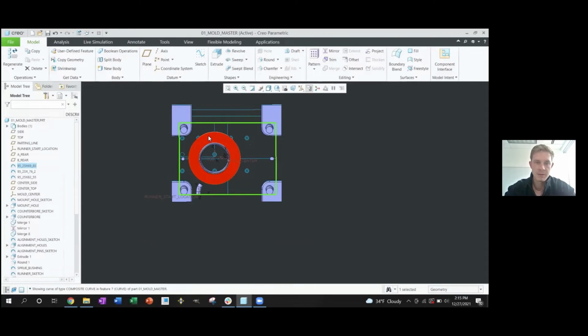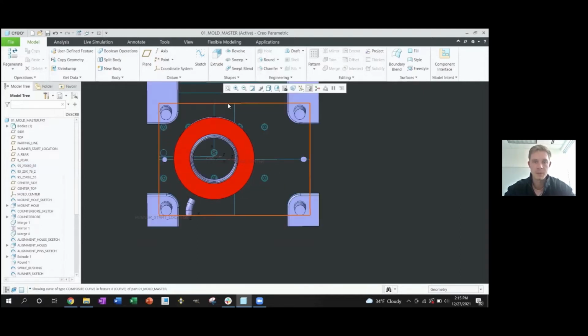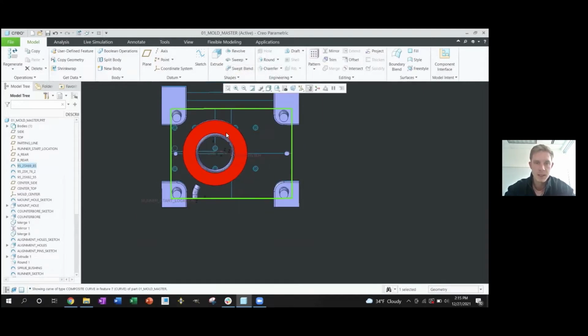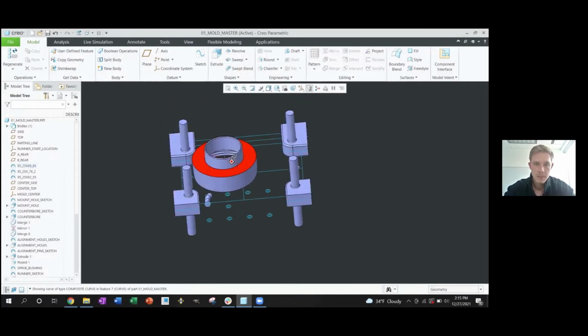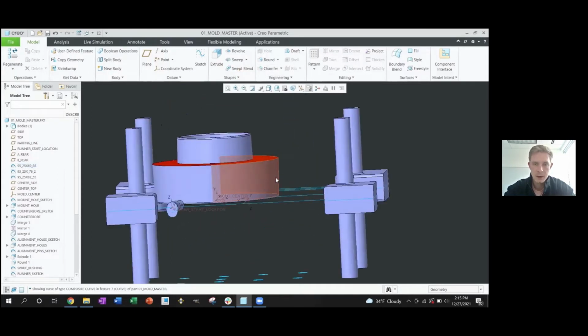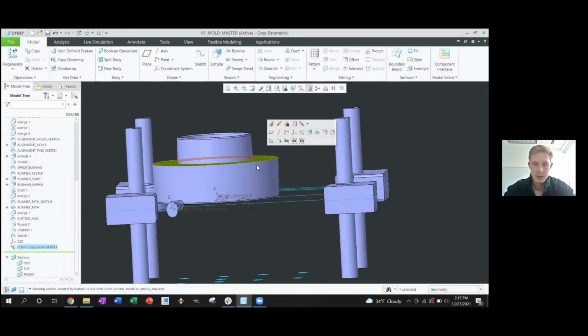If we didn't have the requirement of 10mm wall thickness around this part, then we would have to go to a bigger block size depending on what that part dimension might be. But for this mold design, we're going to be able to use the smallest pocket size. If we look at the side view of our part here, we can see that we're going with this top parting line.